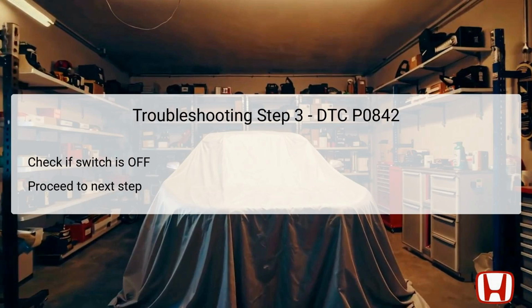If it is off, this leads you to the next diagnostic steps for proper troubleshooting. If the switch is on, this could indicate a persistent fault that needs deeper inspection, and you would then move on to more detailed diagnostics per the outlined procedures. It is vital to assess this correctly, as it may dictate whether there's a need to replace the pressure switch or investigate issues related to wiring and connections in the system.